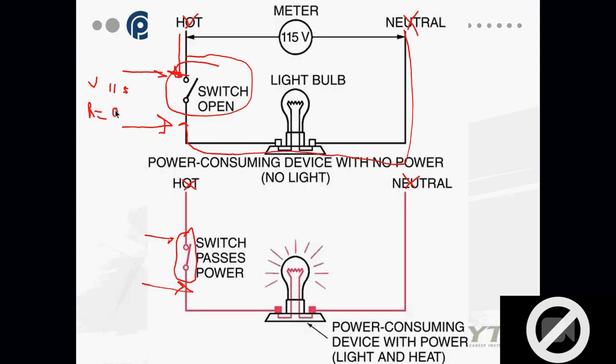OL. Or, what does OL stand for? Open line? Infinite. Open line is correct, okay? I just want to get the word infinite here as many times as I can, because for those of you who have to take licensing tests eventually, it's not going to say OL, it's not going to say open line, it's going to say infinite.